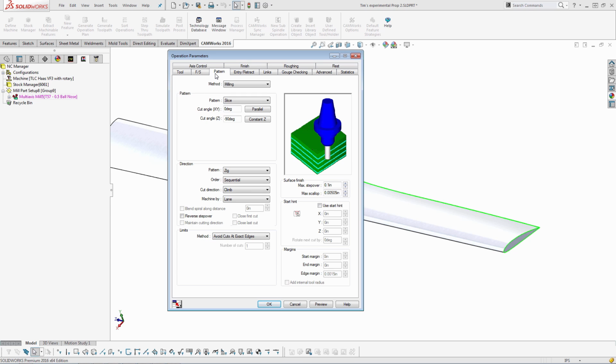It's going to control the shape of the tool path. I'm going to give you my standard workflow on what I like to do. I like to make changes piecemeal, and I like to hit preview a lot. In 3, 4, 5 axis programming, there's always just a few things I do initially to set it up, and then I start making minute changes and programming it visually.